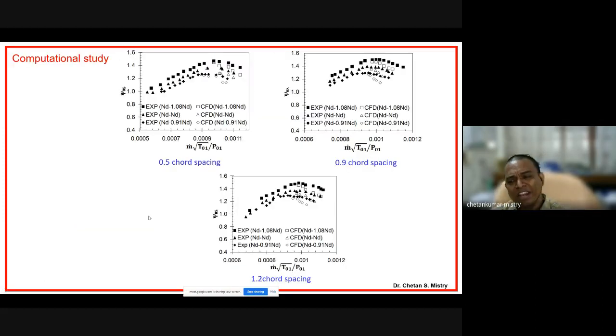This is what we have done in terms of experimentation. Let me come back again. We used our computational tool for the development of rotors, for one design condition. When we did our experimentation, it gave this kind of performance map. Because my second rotor gets stalled, I am unable to do prediction in this particular region. I can predict only up to the first stall or mild stall. I cannot predict this region for all the speed combinations.